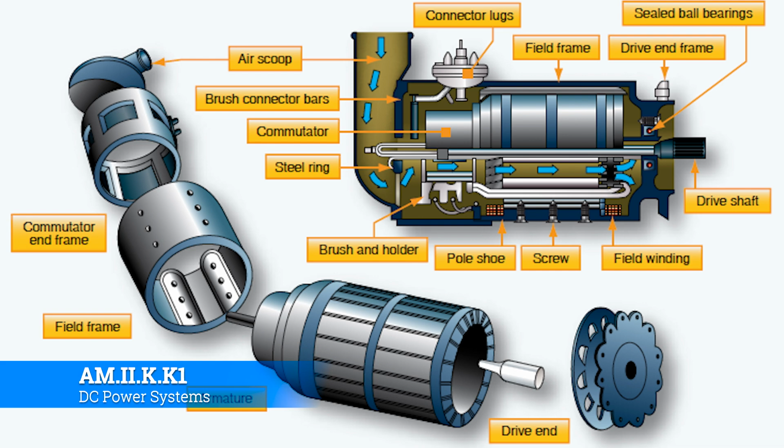Those gears are married up to other devices with gears in them, in this case a generator, which then turns as those primary gears turn. The drive shaft gear starts to turn, and that turns your armature, which then produces your electrical power. So the drive shaft is really important, and we'll talk more about that on the hangar floor as y'all take things on and off.